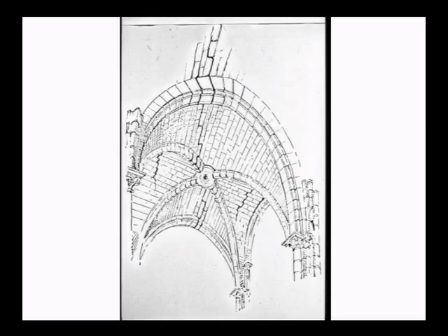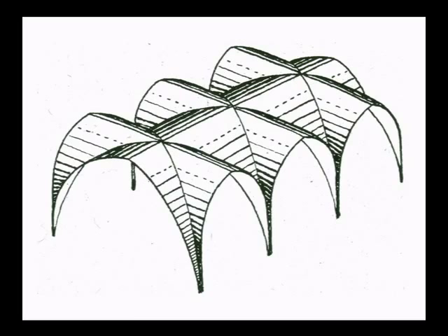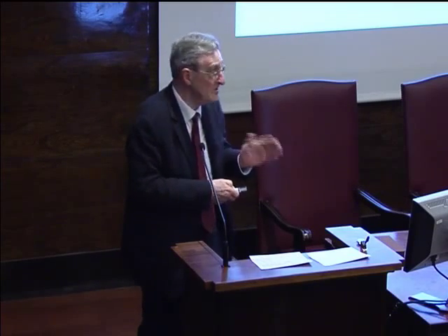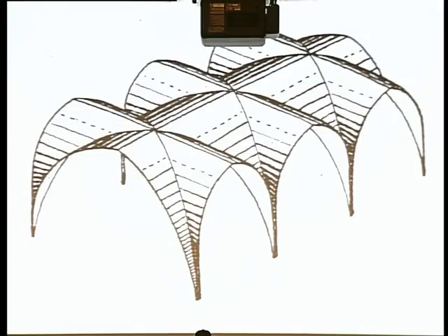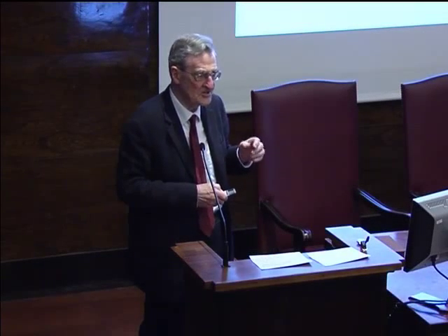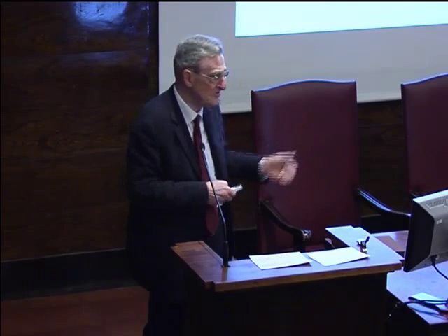This is a hinge. This means that the edge here has pulled away from the supporting structure. There is a gap there against the masonry. There is no force acting on the edge of this vault, no force acting in this direction, and this is one of those occasions when the forces are transmitted theoretically unchanged through the vault.